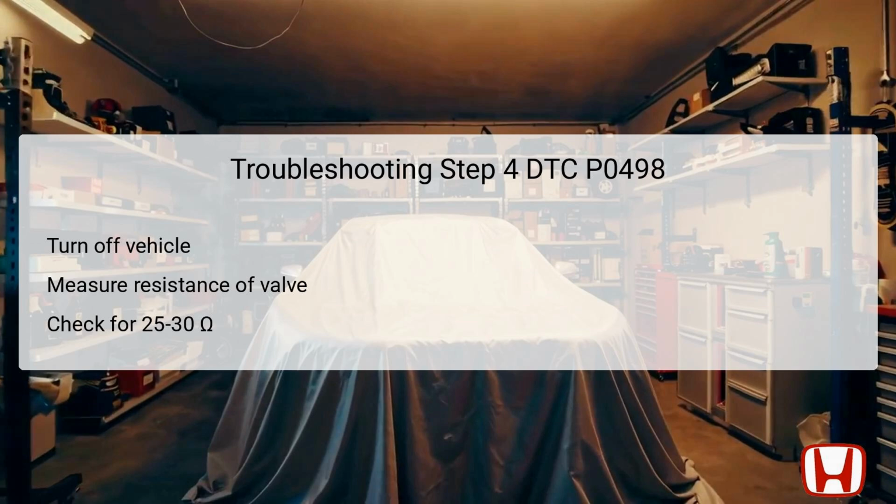This measurement is critical. It confirms the internal integrity of the valve itself. If the resistance falls within this range, the component is deemed functional, allowing you to proceed to the next troubleshooting step. However, if the resistance is outside this specified range, it indicates that the valve has likely failed and needs to be replaced to restore proper functionality.